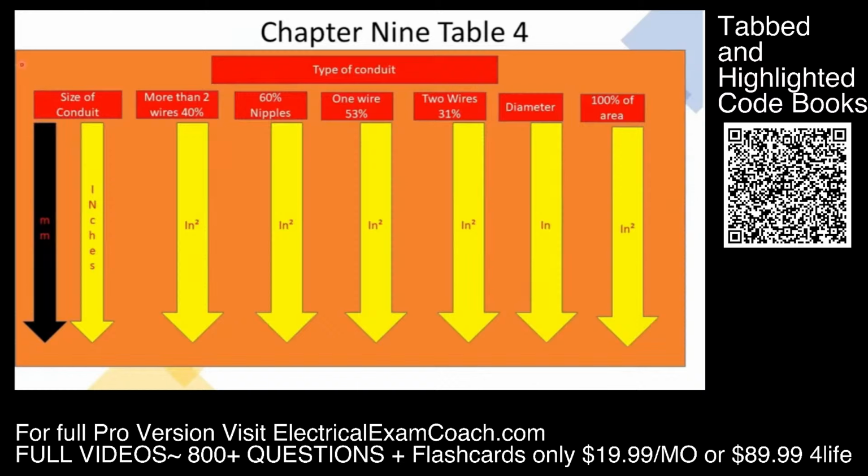Starting on the left-hand side of this table, we're going to find our size of conduit. We want to make sure that we are in the inches column. We're not dealing with millimeters. Then we have a bunch of different columns across the top. The first one is over 2 wires. The second one is 60%, and that's going to be for nipples. Then 1 wire is 53%, 2 wires, then the diameter of the pipe, and then the 100% total fill area. Let's break them down one by one.